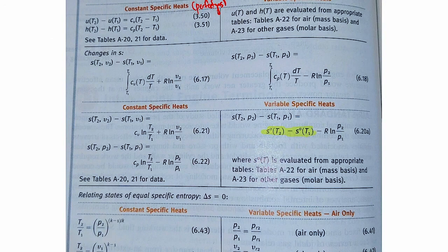The difference in specific entropy is this one right here. Okay, s° is a convenient quantity that we tabulate in the ideal gas tables. It might be less confusing if we used a different symbol than s°. If I just put an alpha there, like alpha at T2 minus alpha at T1, you'd probably get less confused by that. So if you want to calculate the change in specific entropy for an ideal gas, this is how you calculate it. There's a temperature component and a pressure component.